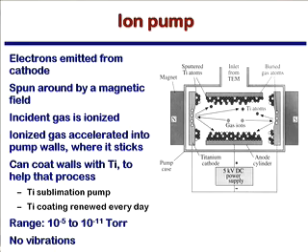The idea here is that you have basically a box that has an anode and a cathode. You have a system of ions that will come off of this anode and cathode as you go through. You're basically having a field emission or a thermionic emission process where these things are coming out. And then you use a magnetic field to spin these things around so that these ions are moving around. And if they encounter a gas molecule, what will happen is they'll knock them into the walls of the ion pump where they stick. And usually what you do is you coat the walls with titanium.